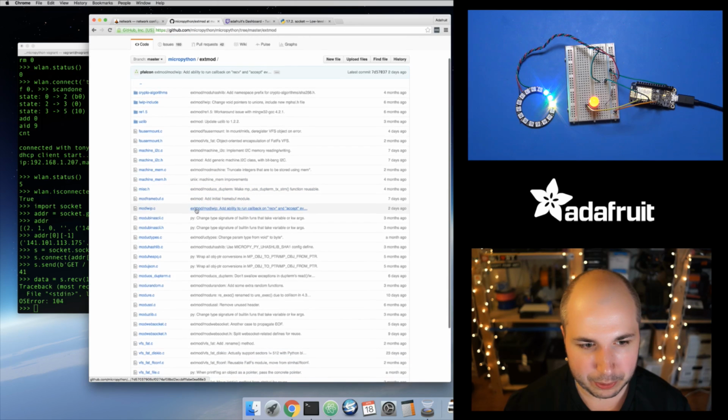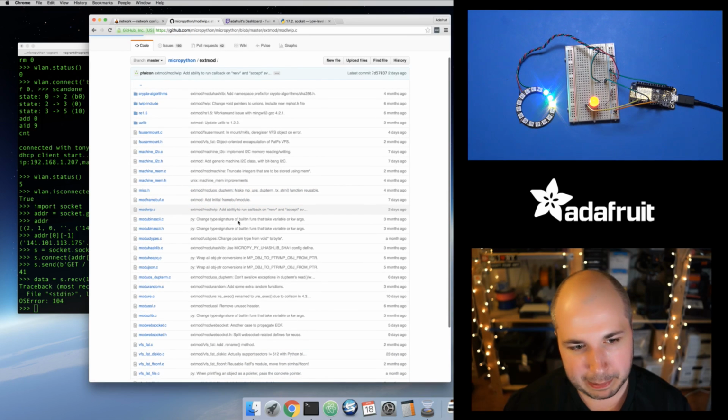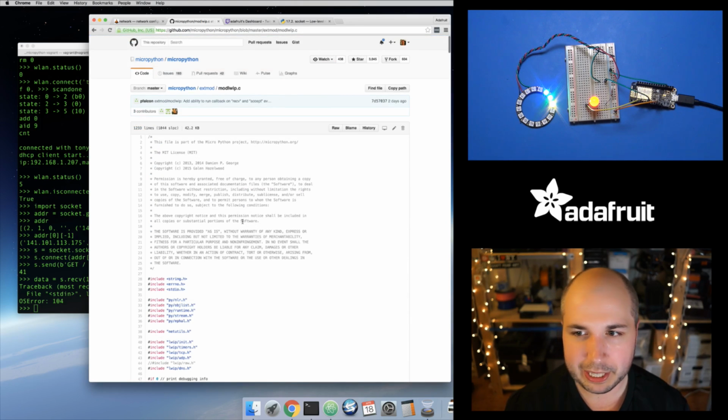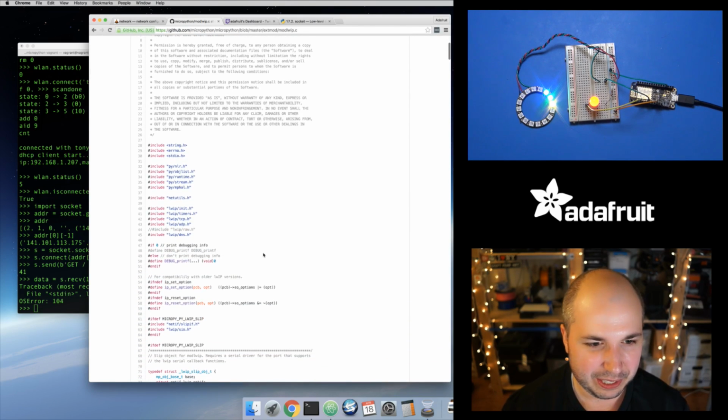modules live. And so the mod LWIP.c, this is the lightweight internet protocol, the lwIP library that they're using. It's basically an embedded TCP/IP stack, a nice open source project, so really nice that MicroPython can pull that in. They don't have to write their own IP stack, because you don't want to do that unless you want to be chasing crazy bugs for a long time.